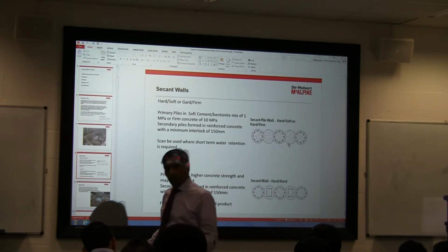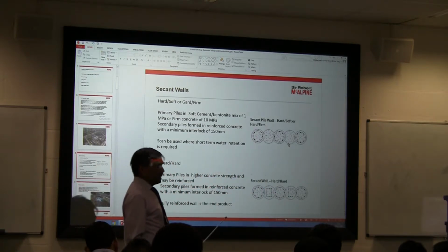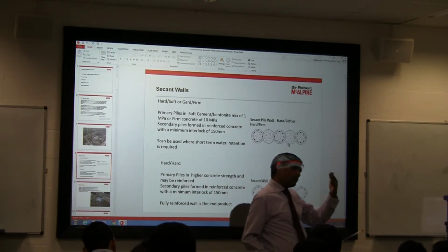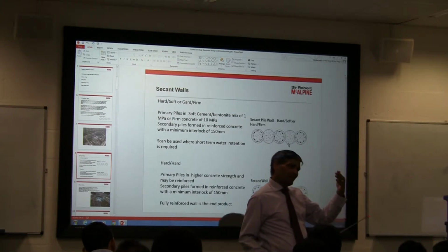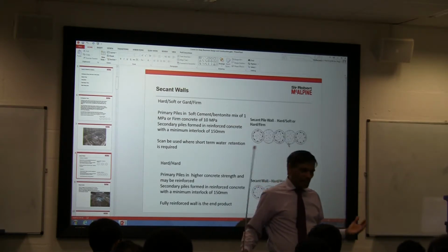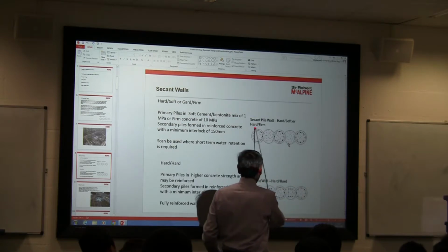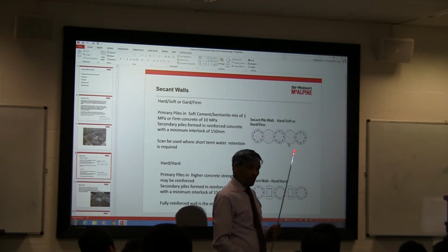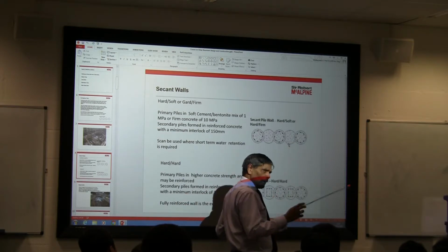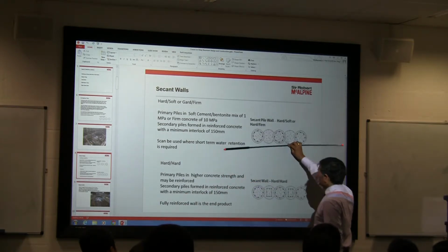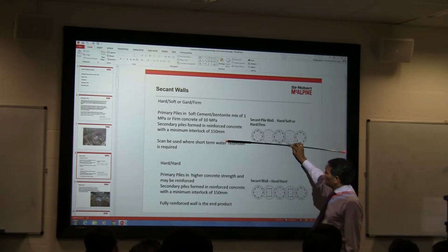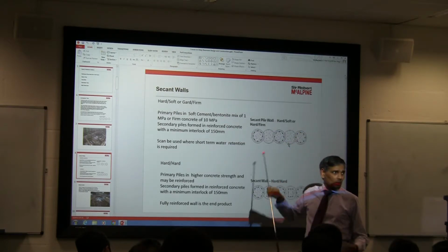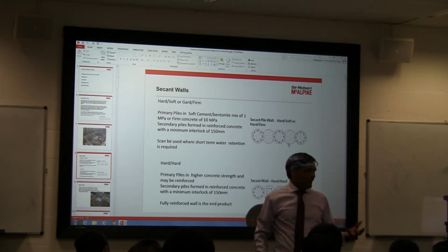But think in terms of the ground. What happens to the ground? If I've got space, I can put a very large diameter pile and let it hold. If I've got space. Remember, the client's borderline, the client's legal line is there. The more you come into his space, the less rentability he is getting.